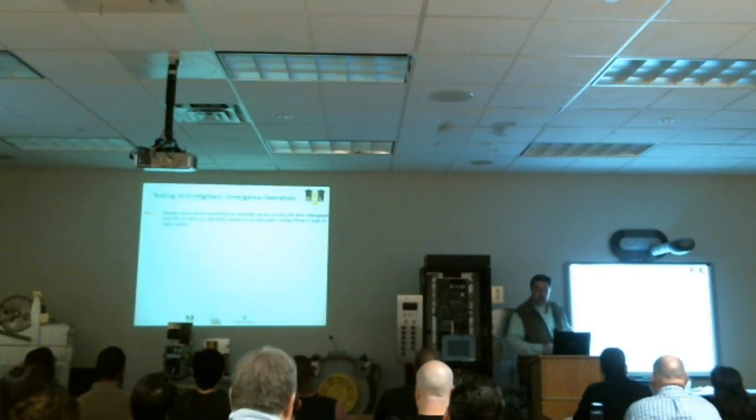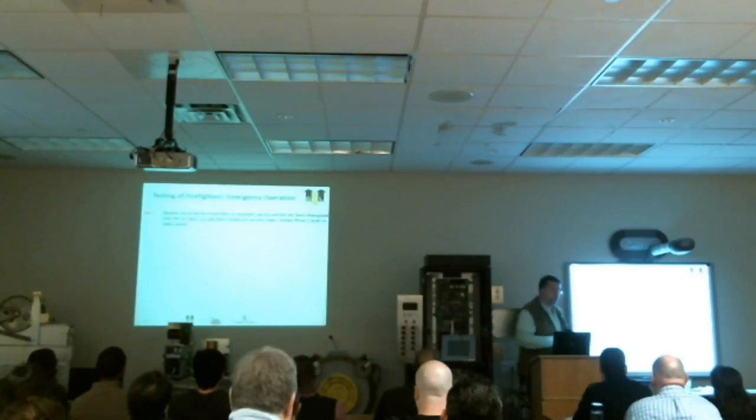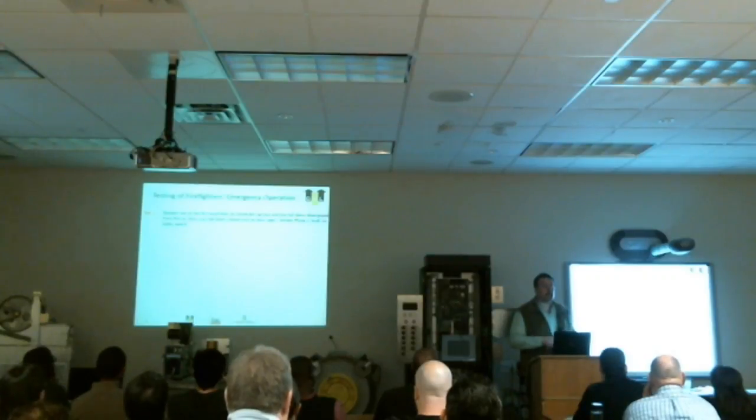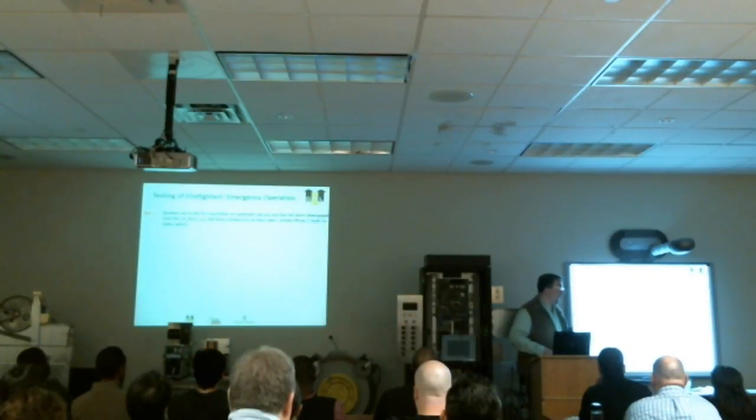The first test: they have the elevator somewhere up the shaft on automatic operation, and they create a fault condition. Doors are open, somebody bypasses the door lock, and the elevator shuts down the way it's supposed to. Now somebody goes in there and hits the phase 1 key switch. Now, right? What should happen?